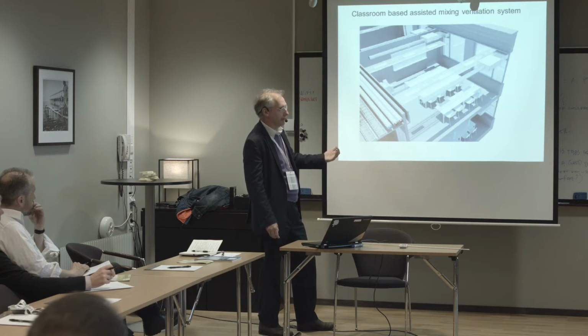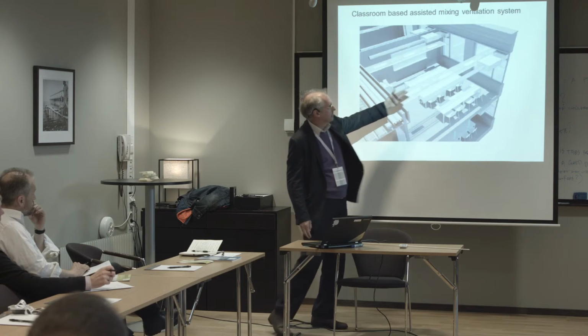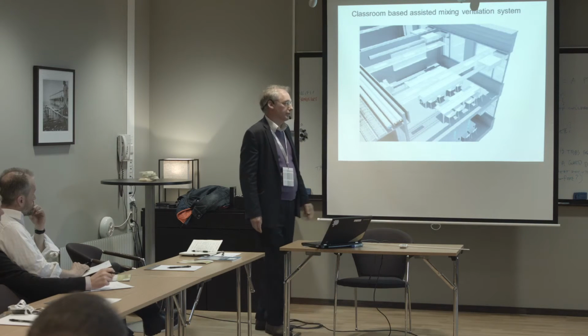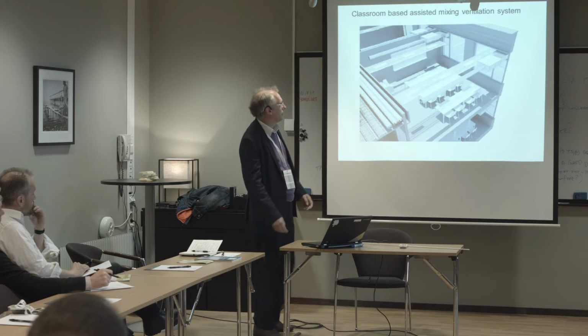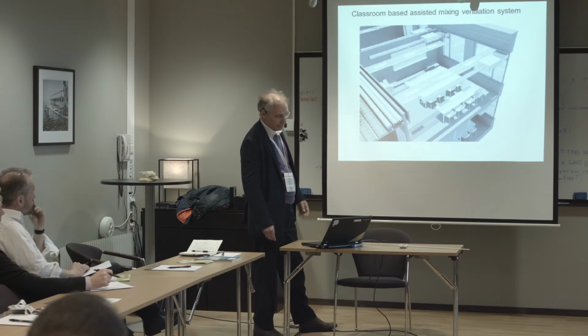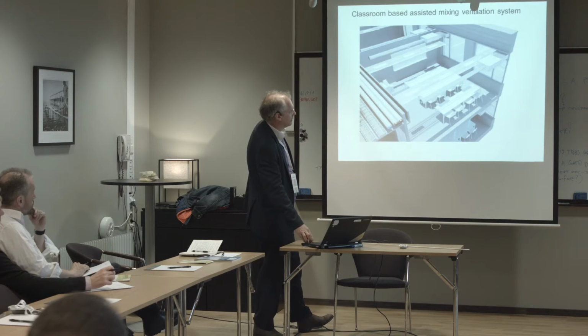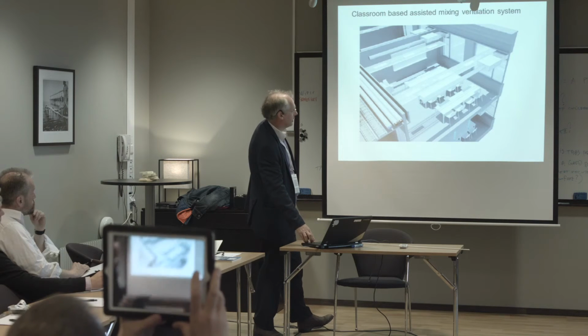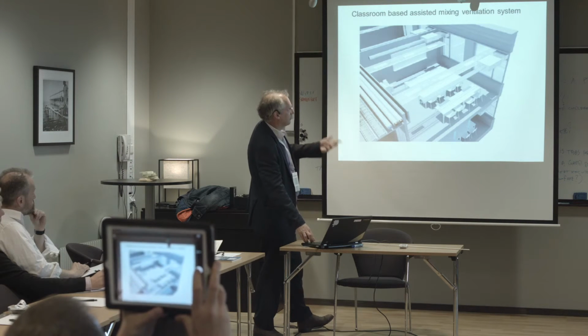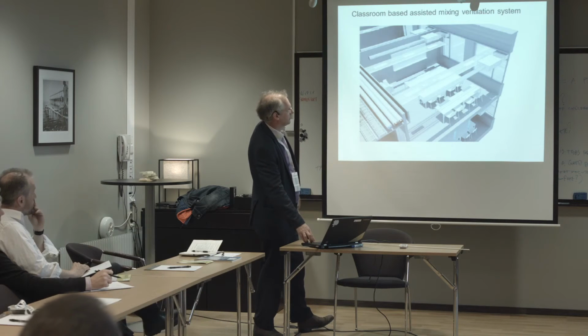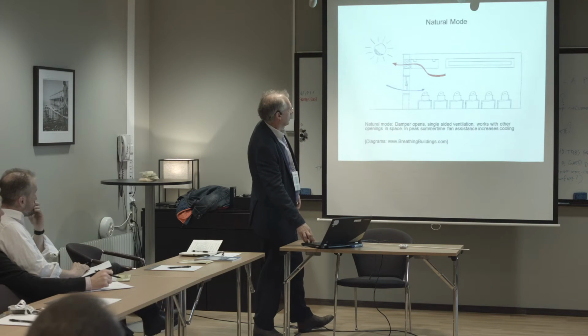temperature up above 15. And we've got a cloth duct to diffuse the air, so that it is not uncomfortable. And that's a very, very simple system with minimal maintenance. And it can be exposed in the room with an exposed slab and working with the night cooling as well. So that's it working in natural mode.